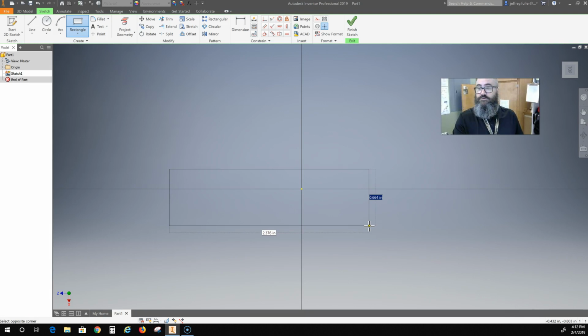So I just type the number 2, and I can hit enter from this point, and it will interpret that to mean 2 inches. If you need feet, then you would need to type the letters FT for feet. Don't use the quotation marks or the apostrophe to indicate feet and inches, because Revit doesn't like, not Revit, Inventor does not like that punctuation. So I can type 2, or I can type 2IN for 2 inches, and it will interpret that for me.